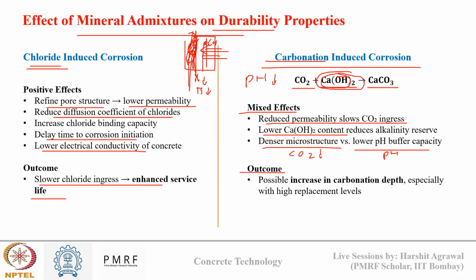So what is the outcome? Possibly you will see an increased carbonation depth at higher replacement levels of SCMs, because there is no Ca(OH)2 present to react with CO2. So CO2 will penetrate deeper inside concrete rather than getting reacted near the surface of concrete.